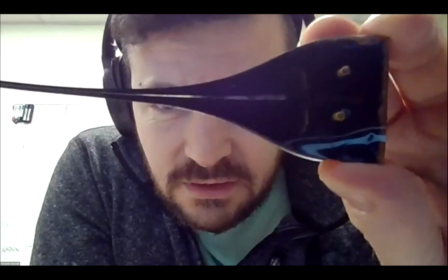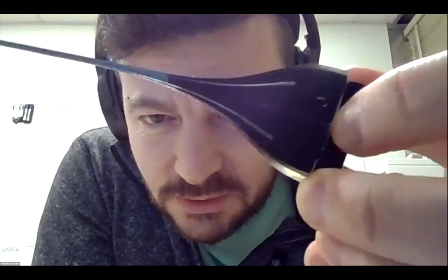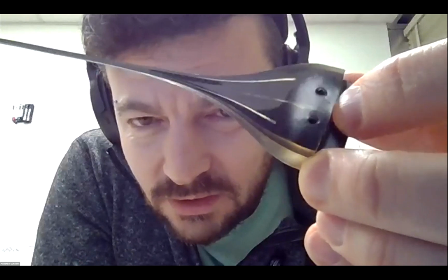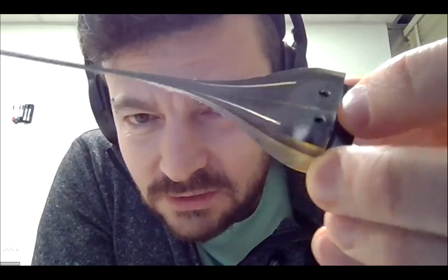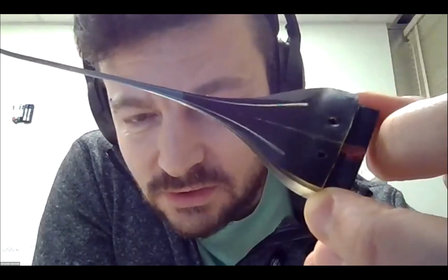Has, if you can see, one electrode on one side and two electrodes on the other side. And in between those electrodes, you have a thin layer of semiconductor. So this is a field effect transistor. Source, gate, source, drain, gate.